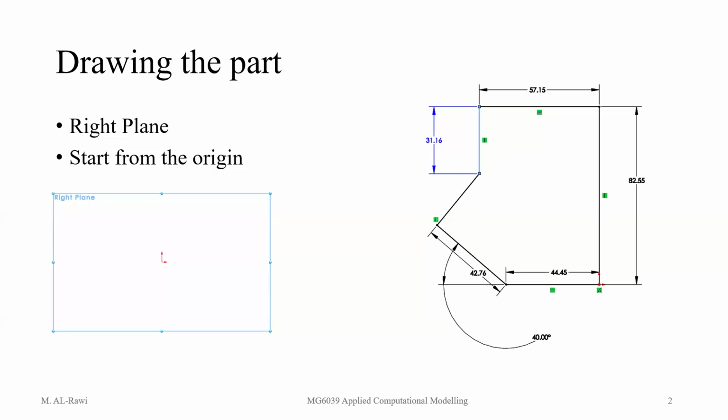Take your time. If you have a question, you need to start sketch. Click on sketch. And then you start sketching lines. Select lines. So right plane face you, click sketch, and then you select line. So all this drawing is by line. You start from the origin, you go up 82.5. Make sure you set up yours in millimeters. Your units are at the corner.